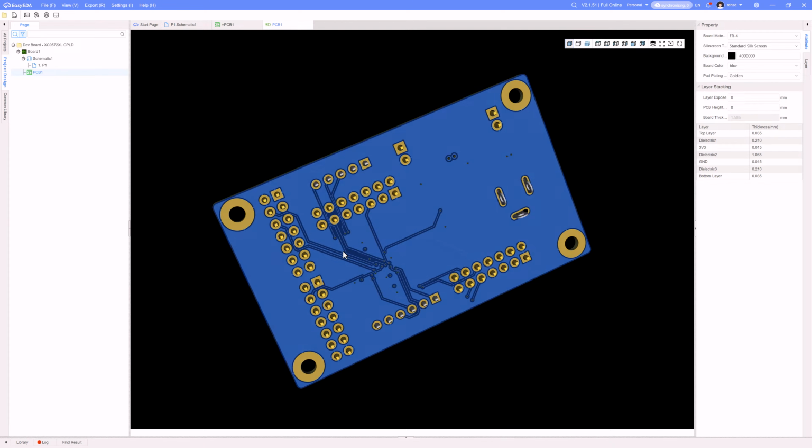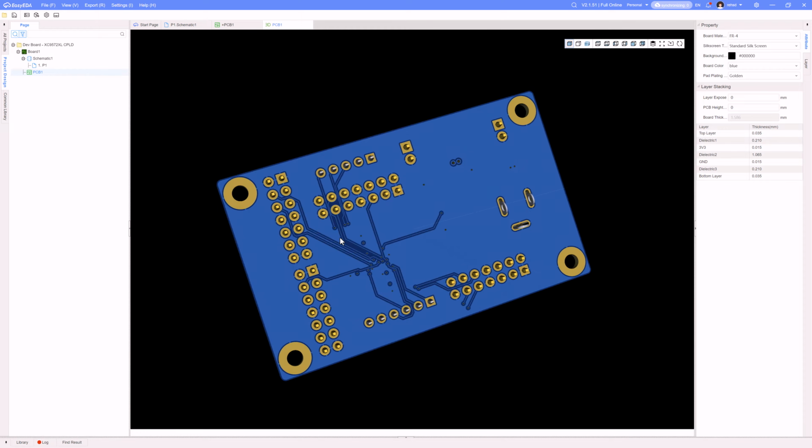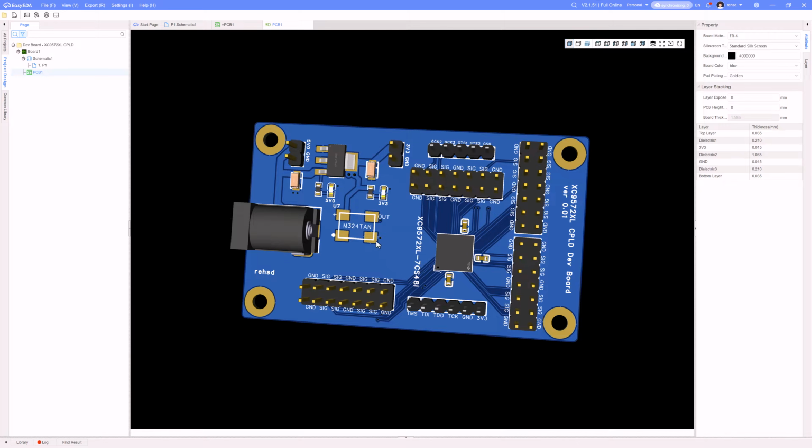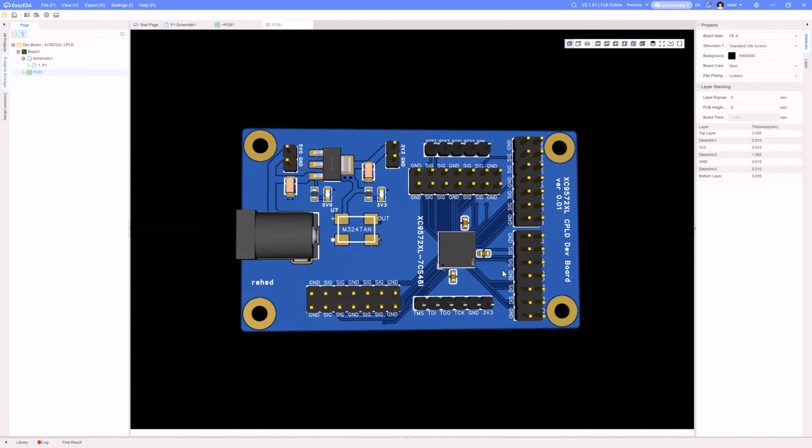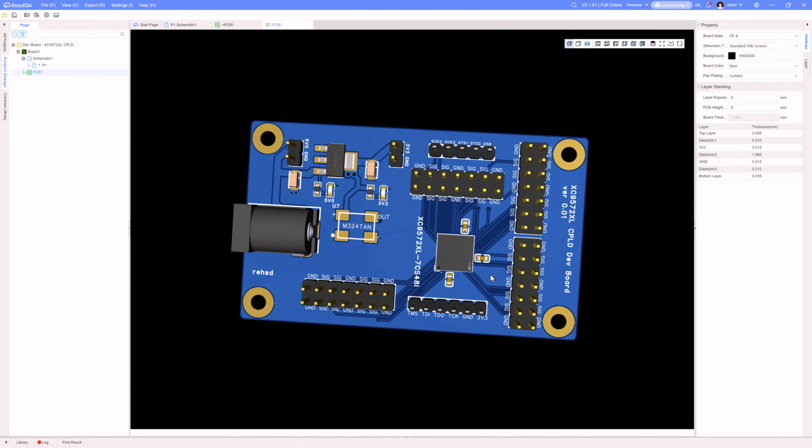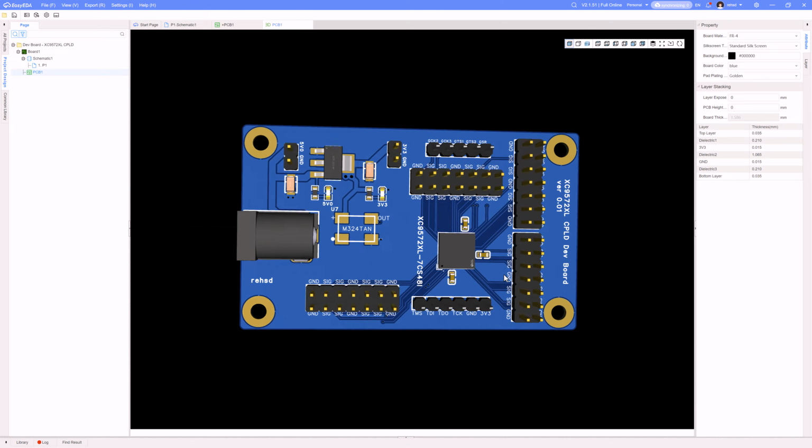If I look at the back side, that's what we're looking at. So all filled in with ground. Top, you can see where it's mostly filled in with ground. There's some here that didn't fill in with ground. These areas is where it didn't fill in with ground, which is fine. That doesn't matter. I've got an inner ground layer and an inner 3v3. That's all looking pretty good.